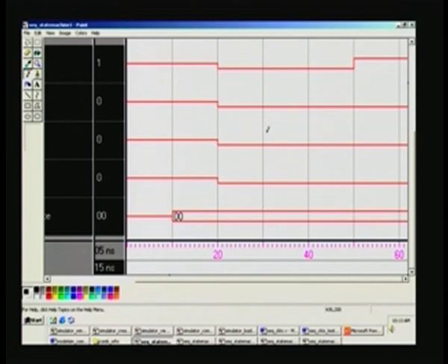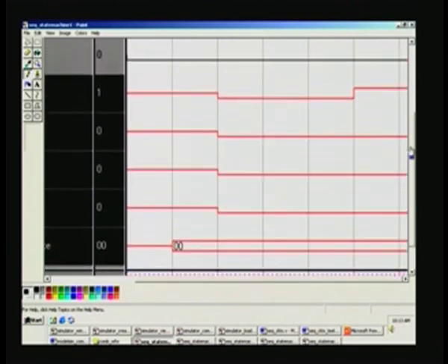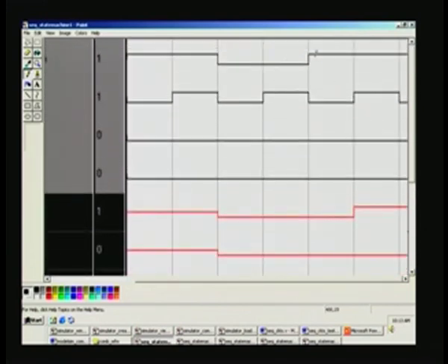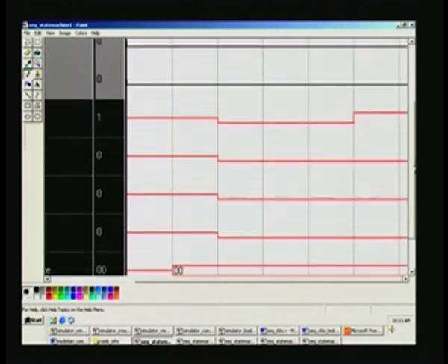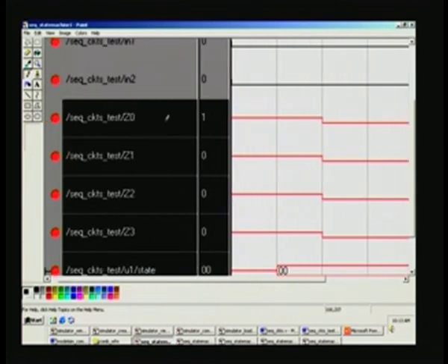There is nothing much to convey except that all the lamps are 0, and at this point of time the real S0 state comes into play, because reset is removed, and following the positive edge of the clock only it starts getting activated, and right at that point of time it enters the S0 state and activates Z0 there, right.